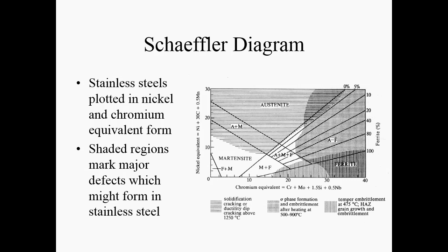That's sometimes quite necessary, because sometimes the supplier will send you a steel and claim that it's martensitic, and it turns out to be ferritic. Because it meets the strength requirements, you're being delivered against a mechanical specification, doesn't mean that it's delivered against the chemical specification, and you may need to check.